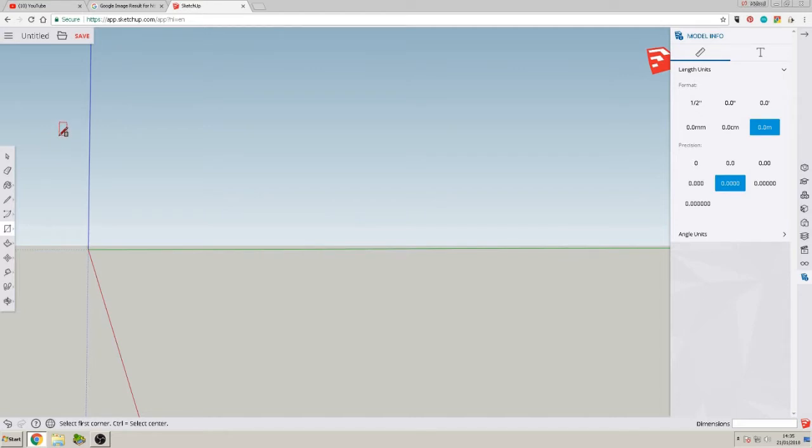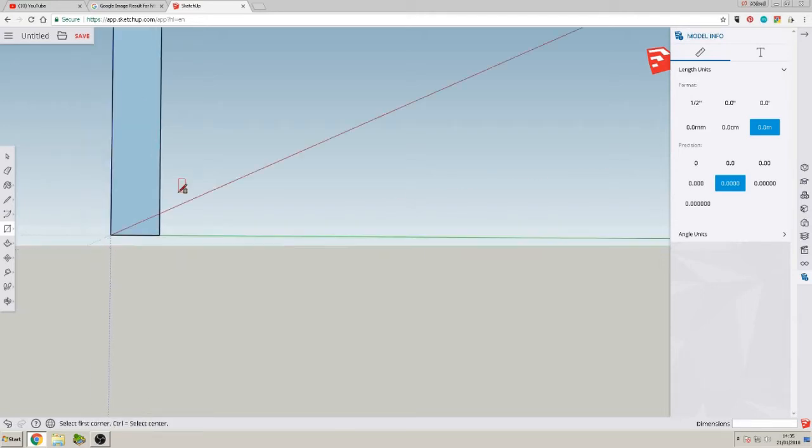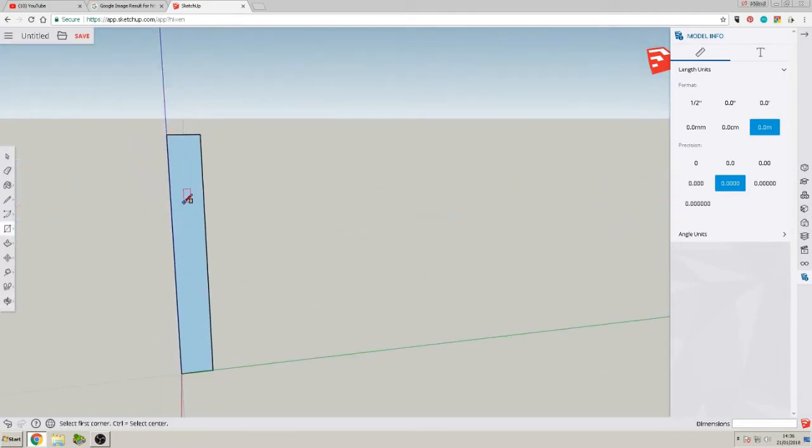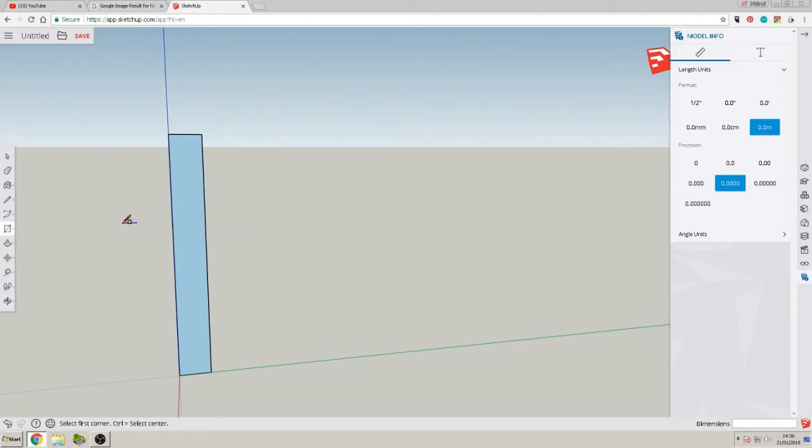You know, when you work with SketchUp at small scales, it can give you strange errors because of the way it calculates stuff, probably. So yeah, we're going to do an M8 thread. So it's going to be, well, let's call it 8 by 1, just to see what orientation we're in. 8 by 1. Okay. Maybe we don't want it like that. Oh no, we do. So that represents a section of 1 millimeter.